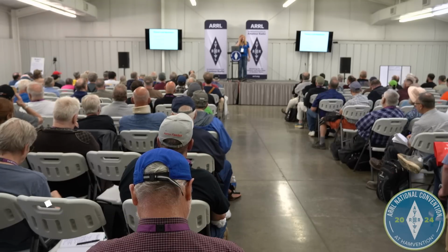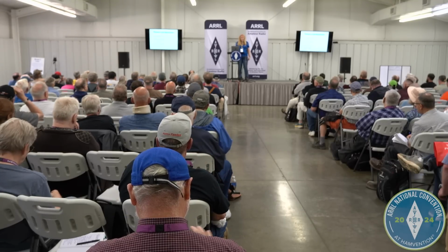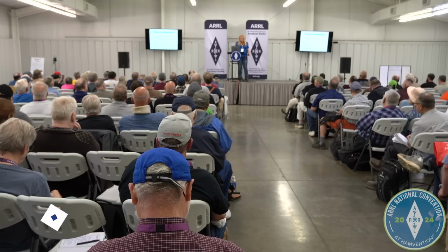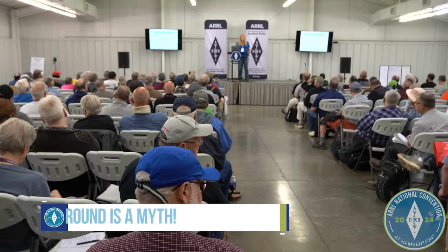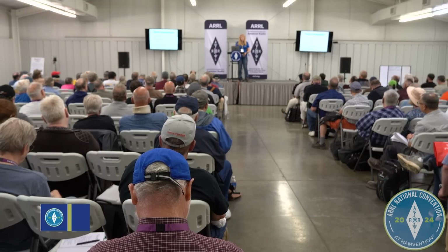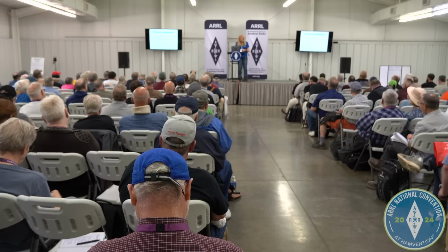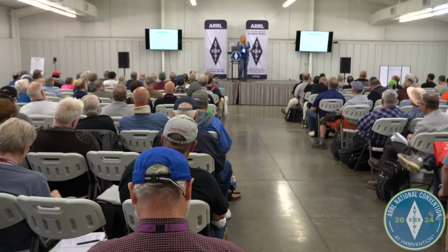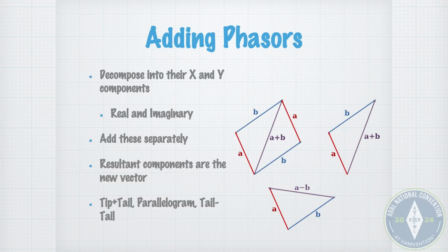They give you little calculations you have to do for an RLC circuit and maybe just an LC circuit. And you have to figure out maybe what the impedance is or how much current is flowing and that kind of stuff. And you can do that really easily using phasors. All you do is add the vectors or subtract the vectors. It's really easy, and that's a very standard process. So anyway, if you get a chance and you need to do a calculation like that, put the differential equations book in the drawer and use the phasors if that's appropriate.